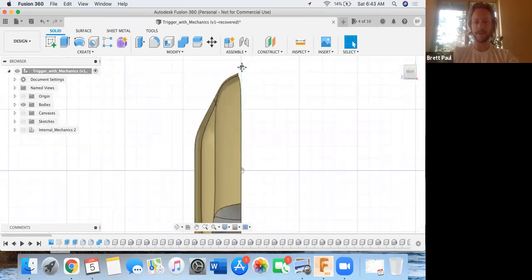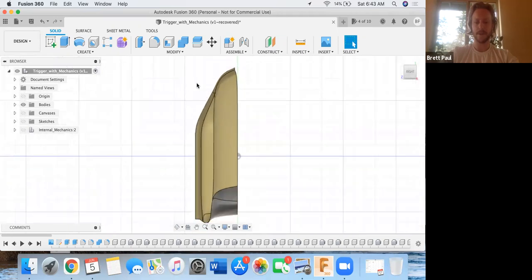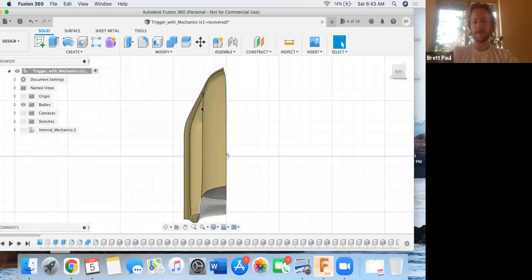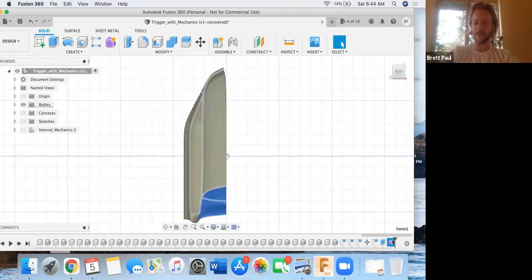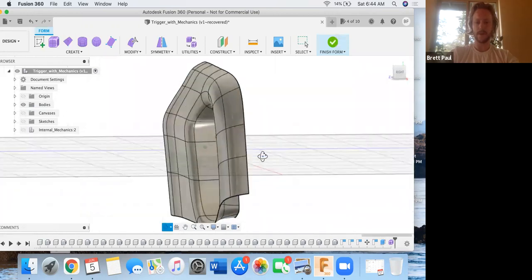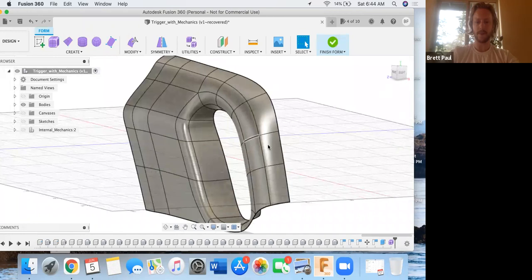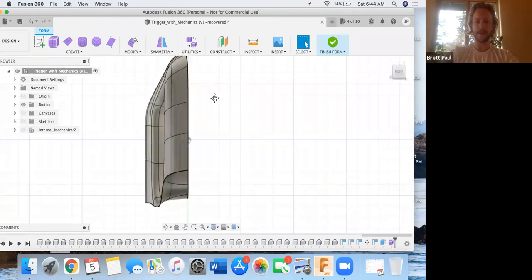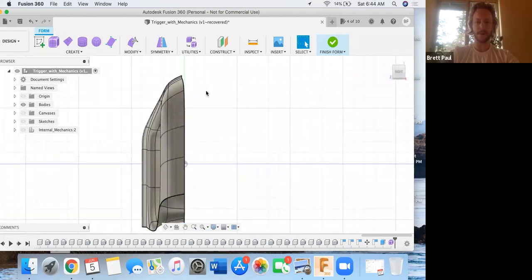So what they're having us do is select all of the vertices. Before we can select anything, actually we need to go into edit form. So you can see in our timeline here, there's just a ton of different steps involved. And so we're going to swing all the way over to the right, and we've got our form here, which is the case itself. We're going to right click and click edit. Okay, so that should get us back to a more familiar look with all the different panels and such. Okay, back on the right side, now we can select vertices as we want to.